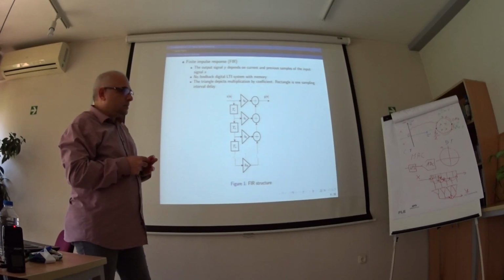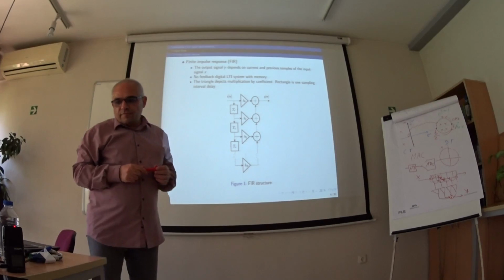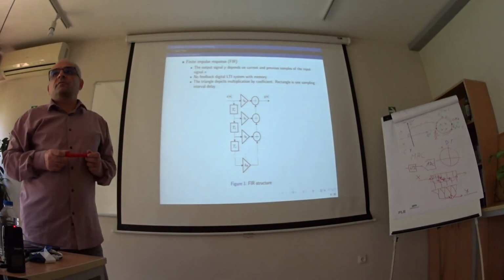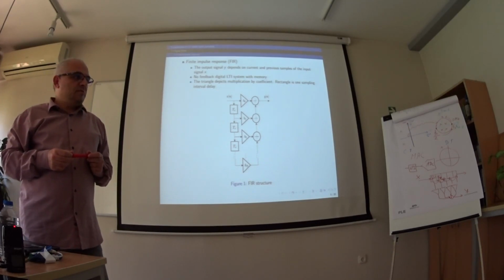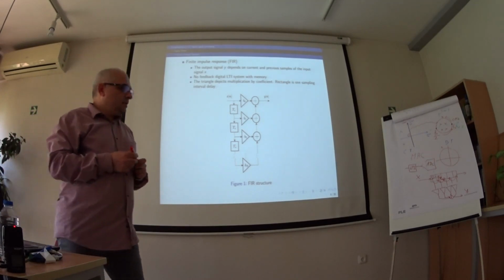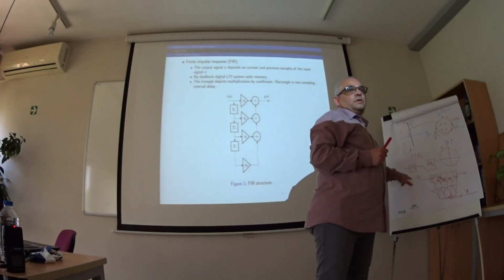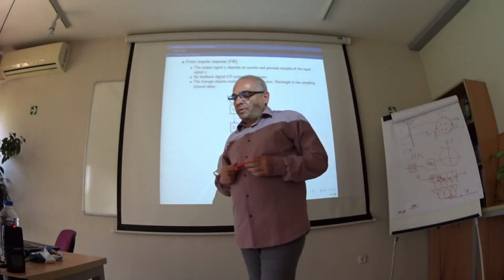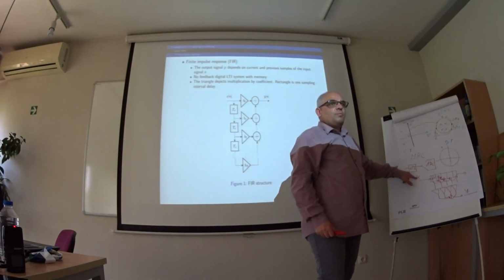So, the answer to your question. This filter has a unique property of linear phase response. Linear phase response is sometimes very desirable because we don't have phase distortion. Do you agree that every filter delays the output signal with respect to the input? Of course. But our input signal has a lot of spectral components.